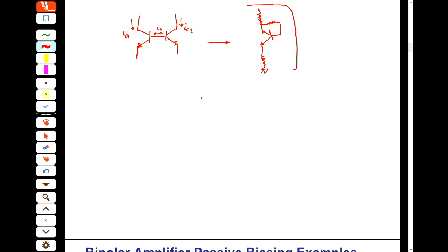So this is a current source, I mean here, not this one. This is, we can say, a current source, and then exactly the same current we have in the other. You can select a number for these. We will see how we are going to do the active biasing. You can select a number, for example, for this IB, and then based on this IB, you have to find the value for this one, and then find the values for R1 and R2 and R3.